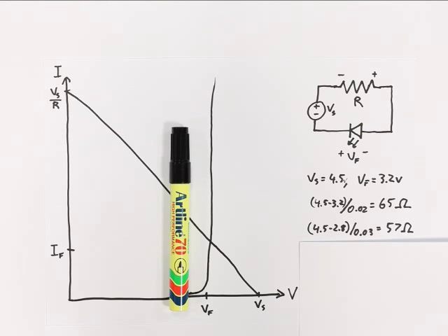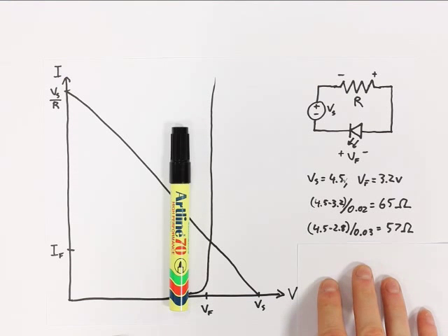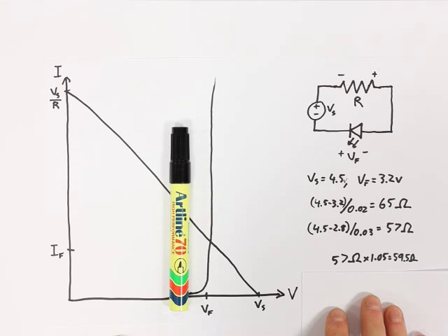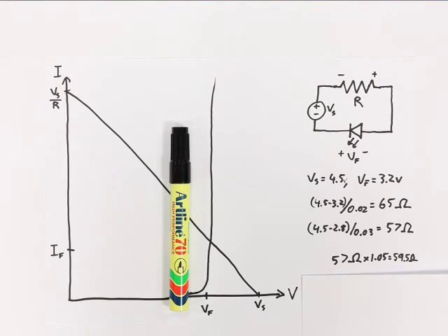Resistors do not have exact values. They come with a tolerance rating, and a typical tolerance is 5%, meaning that their actual resistance could be 5% higher or lower than their rating. So we'll need to assume that our resistor could turn out to be up to 5% lower than its rating, and to counteract that, we'll add an extra 5% to get an actual resistance value that we can use. There we have it, 57 ohms plus 5% gives us 59.5 ohms.